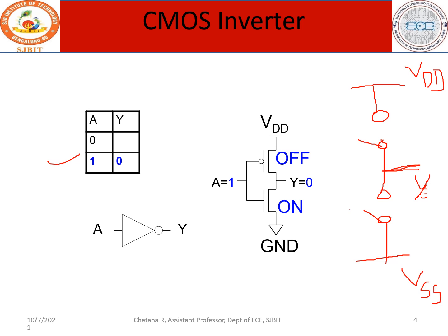What will be the status in PMOS? A is equal to 0, 0 bar is 1. So this is on. So the PMOS device is on. A is equal to 0, 0 bar. Therefore, this status is open circuit. Therefore, the bottom device is off. Now, irrespective of the status of the devices, I am keen on checking the status of Y. What is Y? If I give 5 volts as the supply, as VDD, the entire 5 volts will come here.